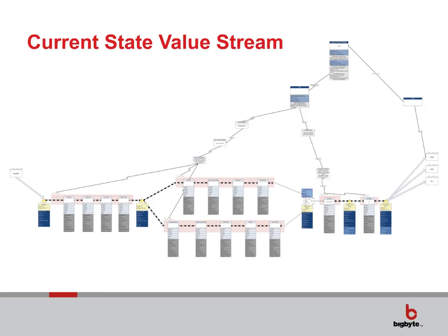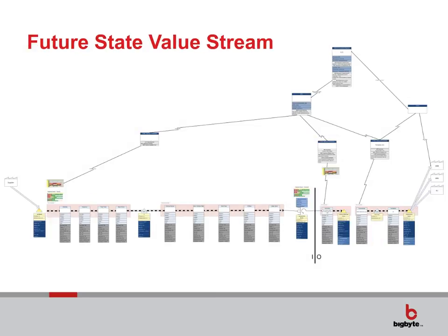So let's look at an example. We're looking at a current state value stream map for a factory that is driven completely by a forecast on the finished goods, and the entire material process is a push system, but we want to change that and therefore introduce an inventory order interface right to the downstream side of the Kanban loop, the Kanban control cycle that we can see there.